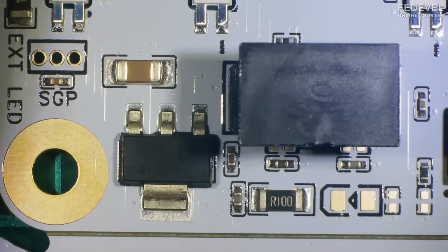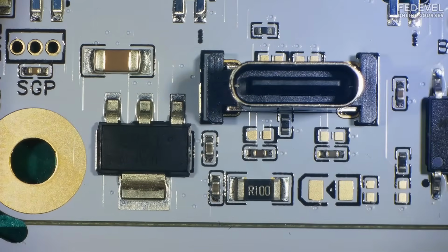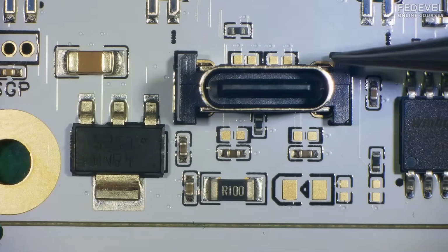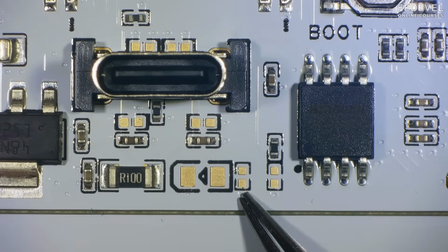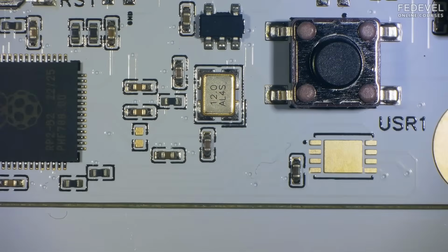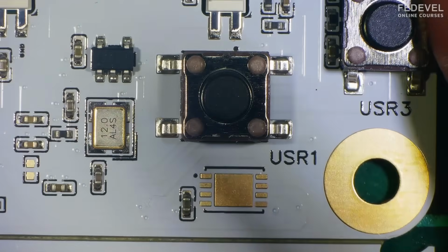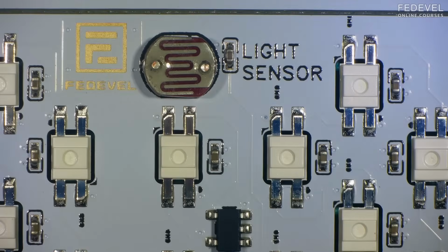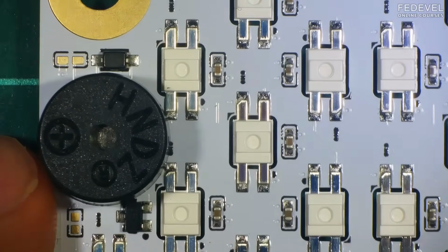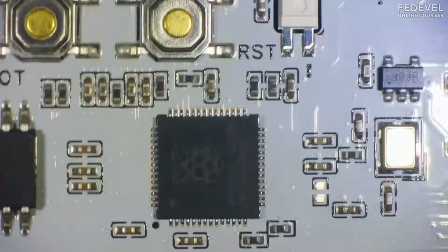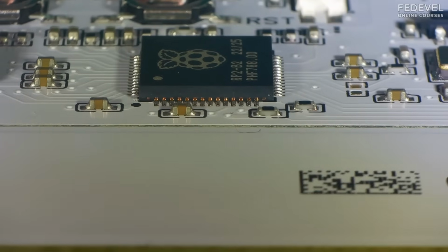So first, after you receive boards, double check the quality of the soldering. You can see ESD protection is missing, LED is not fitted, double check pin 1 position, real-time clock is not fitted, the sensor is here, we will put it on the other side of the board. Double check also if there is no short circuit between the pins.